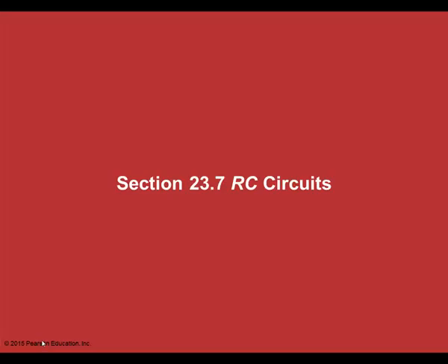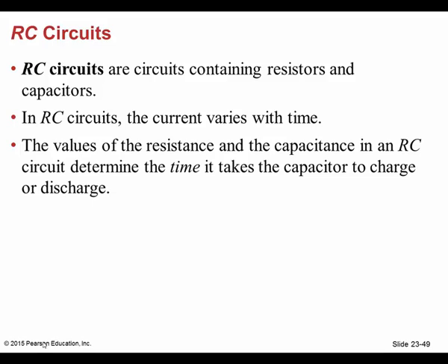All right, now, okay, what about RC circuits? RC circuits are those that contain resistors and capacitors. They are very, very useful. We use them all the time. We use them in electronic components like crazy, cameras especially. Anything that has a time delay as far as charging or discharging capacity built into it. If you flip the switch and it has to charge for a little bit and then it starts operating, or you flip the switch and it discharges and then it starts to operate, this is through the use of what is called an RC circuit, and it's a resistor and a capacitor in combination.